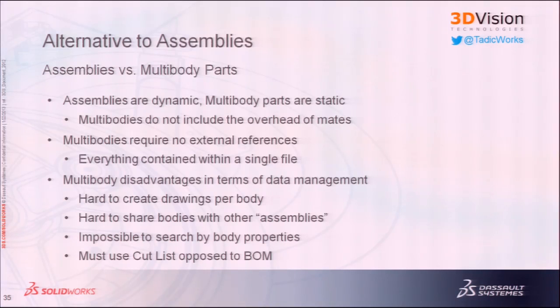Now this is a huge benefit. All right? Everything's contained within a single file. But with that great benefit comes some disadvantages as well. With everything being in just one file, it presents some data management issues. You know, how do we revision manage an individual body inside of a part file with data management software? It gets a little bit tricky, all right? It also makes the process of creating a drawing for an individual body a little bit more involved. I was exaggerating when I said hard, it's just a couple extra clicks, but there are some more steps required to do some other things.